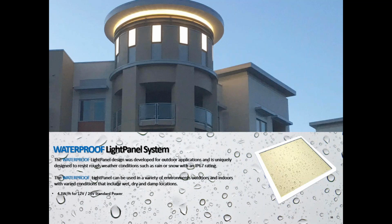And I'd say probably about 92% of the projects that we do, we're always backlighting another material. Here on this tower in San Francisco, we're backlighting a faux onyx on the top of that tower there. So that's a 4 foot by 8 foot waterproof light panel with a piece of faux onyx that was either a resin or an acrylic in front of it, so it protects it from the UV rays. So typically on exterior projects, we're going to be backlighting glass, backlighting another material, maybe some graphic signage.